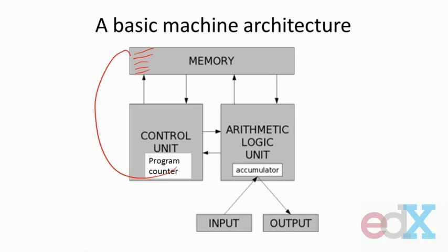And that instruction will typically be something that takes some value out of memory, runs it into the ALU, does some computation, and stores it back in memory. Having done that, the program counter increases by 1, which means it goes to the next instruction. And it executes that instruction, which again typically will be to take some values in memory, run them through the ALU, do a simple computation, and store them back here. And it simply keeps doing that, moving through the sequence of instructions one at a time, doing those very simple arithmetic and logic kinds of computations.